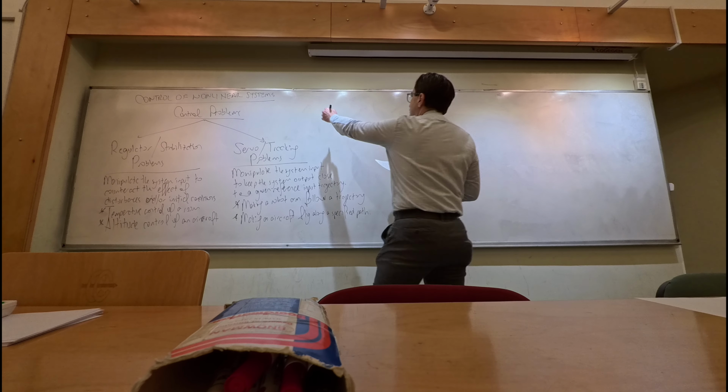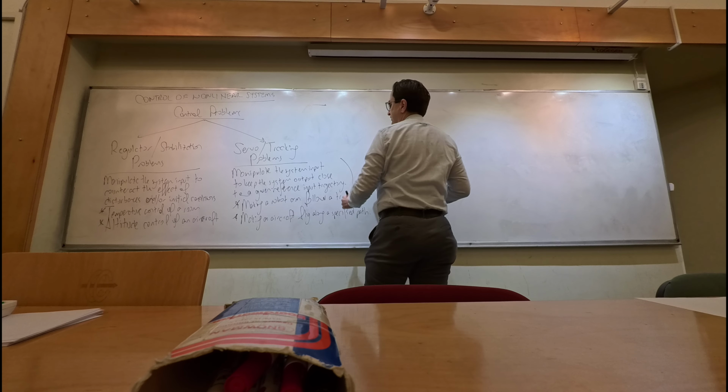The systems which would achieve such tasks are sometimes called servo mechanisms. That is the name given to these systems. For example, you might have heard the name servo motor. It is this type of system. When we have a control loop, we have a controller here that is called a feedback controller. And here is the system that we would like to control, that is called the plant. And that is the feedback loop.